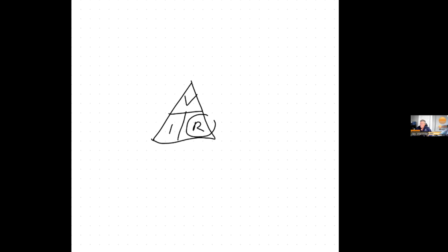Well, let me go ahead and jump into the whiteboard here again. So in the good old days of design, we would have, let's say, a solar array up here. There we go. All right, so that's my array. And let's say I've got 3 strings and I'm going into a combiner box. Well, in a combiner box, these strings are now going to be connected in parallel, and then I'm going to leave here and I'm going to go to my DC disconnect.